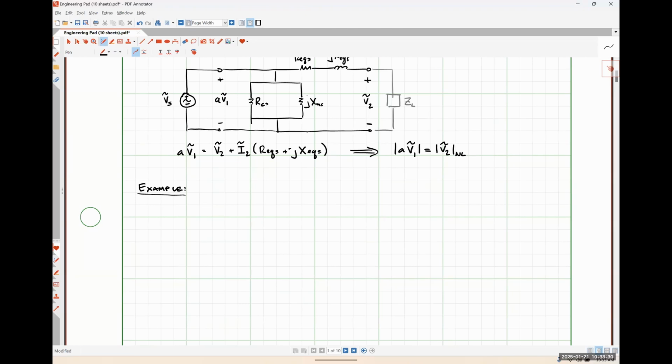For CTs stuff coming up, right? So CTs, current transformers, and VTs are used to measure the signals so that they know when to turn on relays and things like that, throw industrial breakers, or potentially when to engage things like static VAR compensators to make sure that there's enough VARs injected into the system to help it ride through.